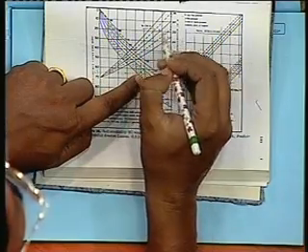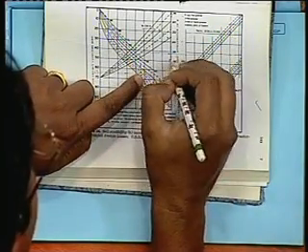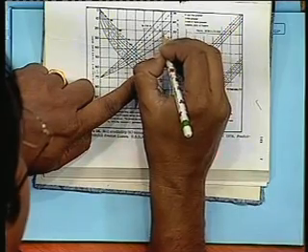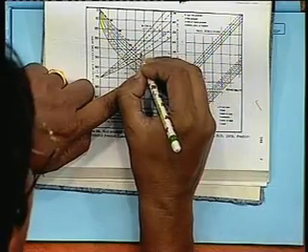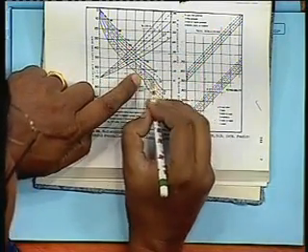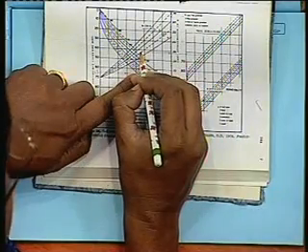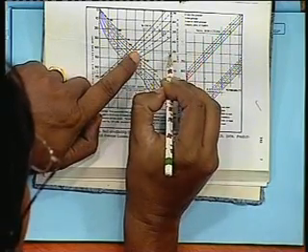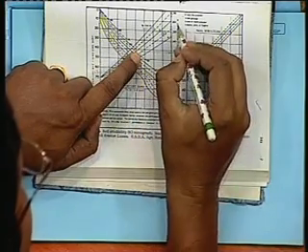Percentage organic matter in the soil. What is the percentage organic matter in the soil? We have found it out to be say 3%. So this value is where the dotted line, if you run parallel to this line, cuts. Okay. Then from here onwards this gives you the first approximate value of K.